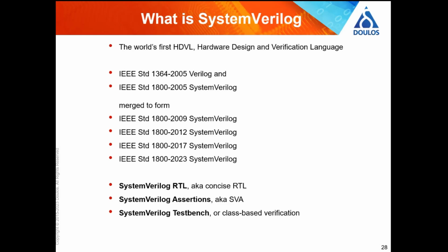So there's SystemVerilog RTL, doing your design. It's not massively different to VHDL, to be honest, a little bit more powerful, but you're constrained by what your synthesizer understands. Your synthesizer can only synthesize RTL, whatever language it's written in. So there are some cool features, but I wouldn't say any more than that. Then you've got a language within a language called SVA, SystemVerilog Assertions. That's for writing the rules that I've been talking about, the so-called properties, assertions. We'll have a look at that in a minute.